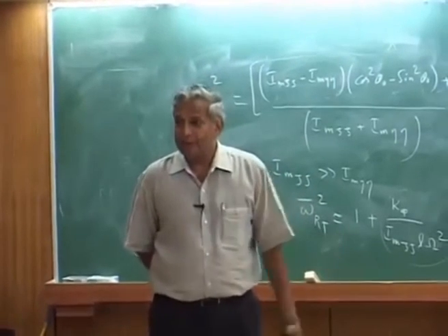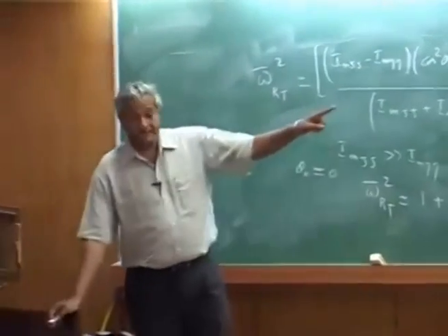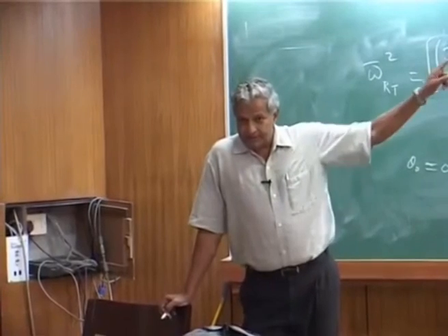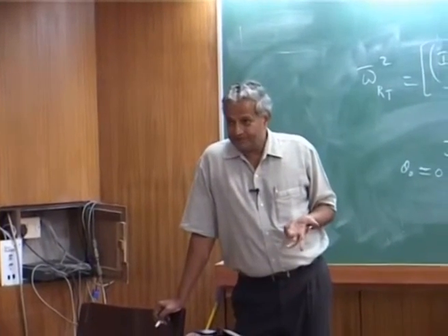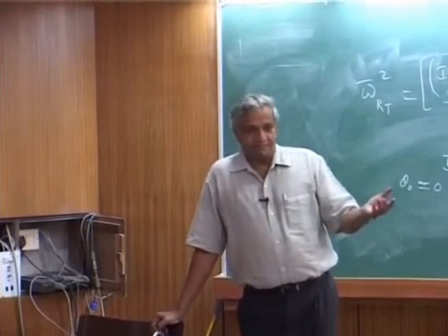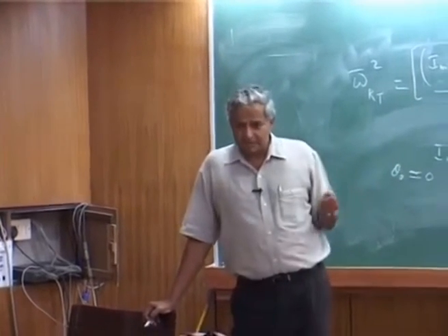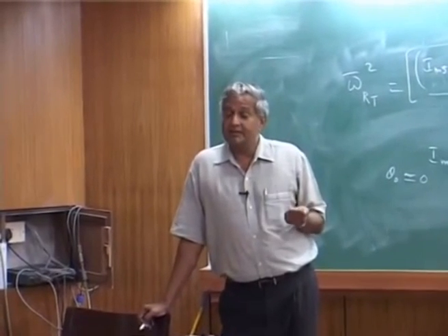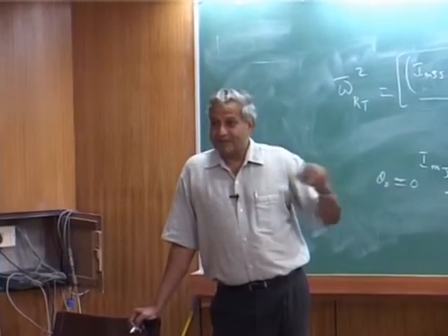So here we will be having an axial term also. Yeah, axial load. But I have made it as a rigid blade. Please understand, in all my assumptions, in all these things, I said my blade is rigid. Okay? But the question is, when you have a centrifugal force, what do you do? There is an axial deformation. Yes, it is there. But then you have to include the axial frequency. Okay, axial mode.